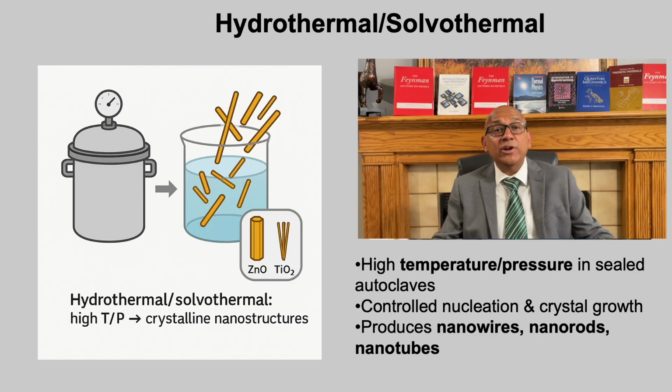Another powerful solution-based synthesis route is the hydrothermal or solvothermal method. In this approach, precursors are dissolved in water or another solvent and heated in a sealed autoclave at high temperatures and pressure. The enclosed environment promotes controlled nucleation and slow crystal growth, leading to highly crystalline products.